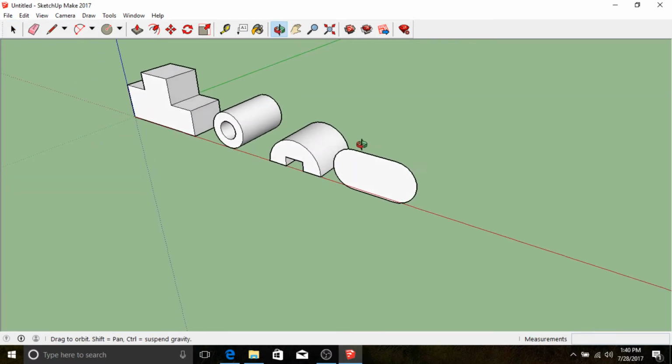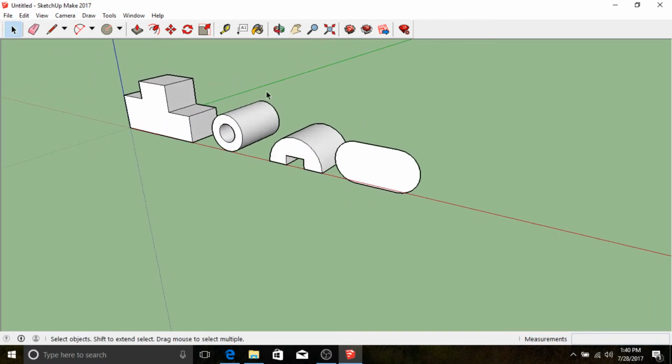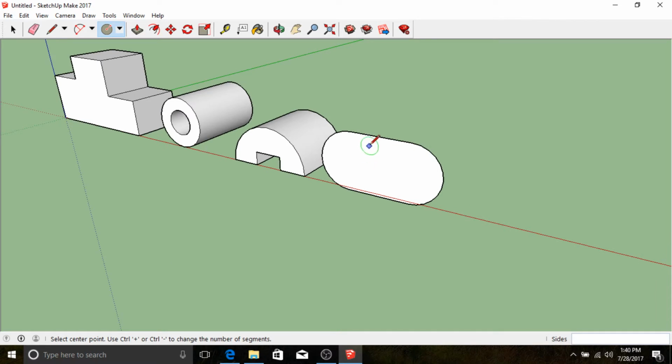And before I extrude, what I'm going to choose to do is put in that circle that belongs in the middle. Now to get it to be exactly in the middle, I'm going to use my inferencing. Right? So if I hover over this midpoint for a few seconds and I start to drag down, you'll see that it's still referencing that point.